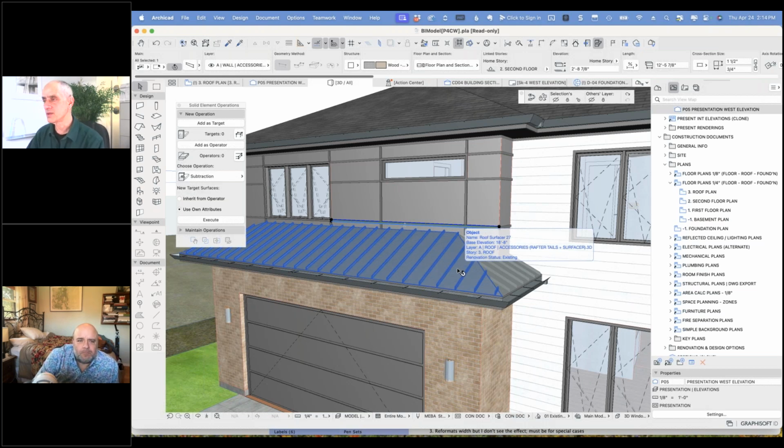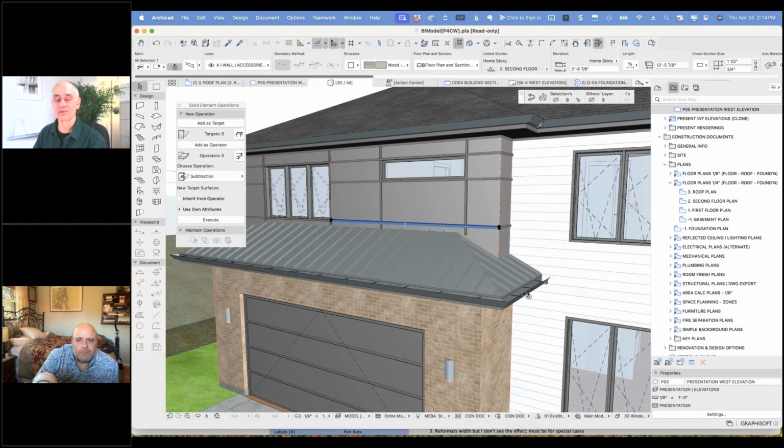And if you had the roof in a different position, the ribs would start in a different place. So if you created another copy of the roof that stuck out, you could control where the origin is, and then you hide that other copy of the roof. That would be, he says, you can select an adjacent roof surface and create a copy and trim to fit.